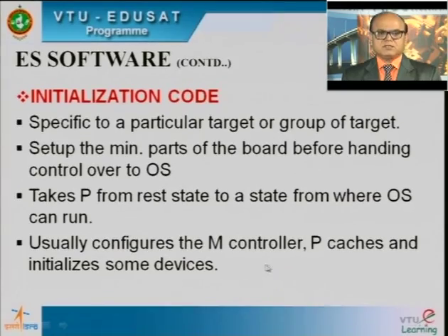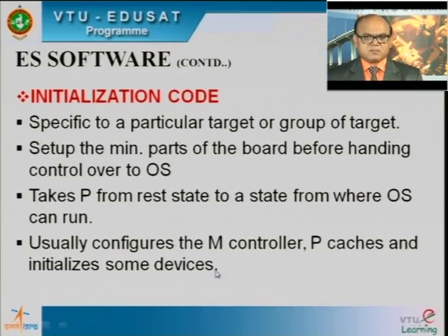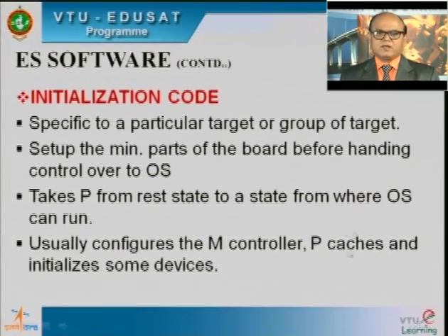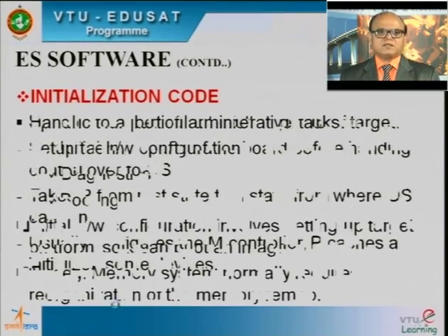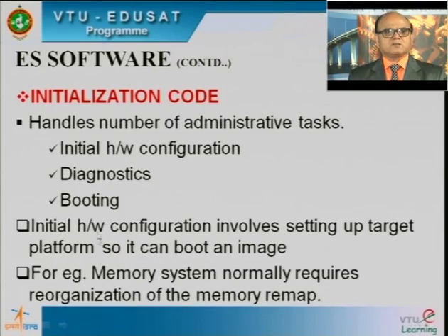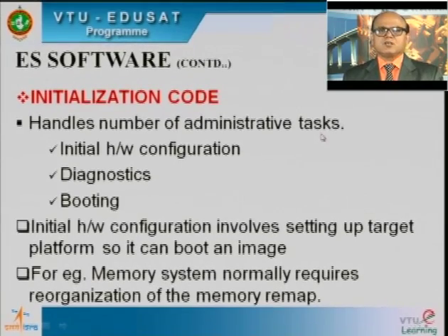So first it has to configure the memory controller, like we took the example of the DRAMs that are to be initialized. Such things are the main things done here, and the processor caches are to be initialized, and some minimum devices are to be initialized. And the initialization code handles a number of administrative tasks before it hands over the control to the OS.